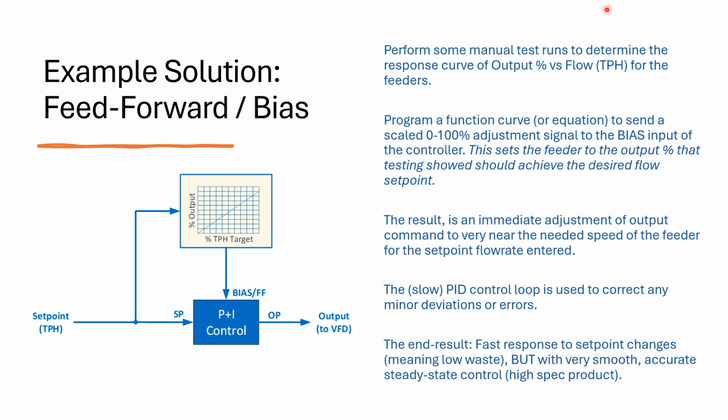So from that scaling, we've got this function curve, which I show as the yellow with the function curve shown there. The set point feeds into a block in the controller, and that block scales to produce a rough bias signal. It's basically just a percentage that biases the controller. That bias just adjusts the output by whatever amount you say based on how you set up the PID block and so forth.